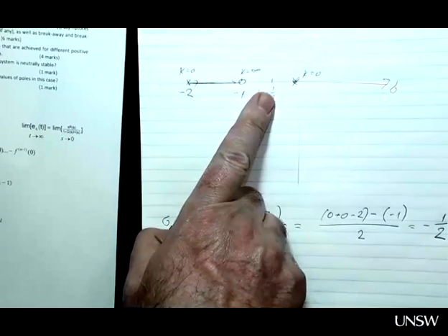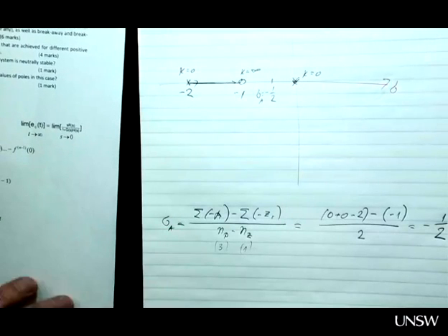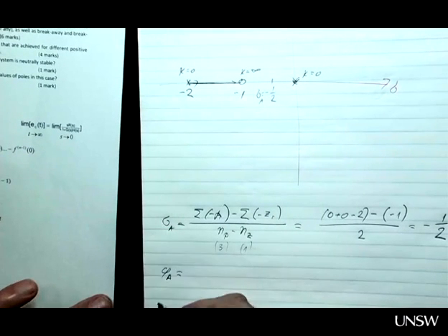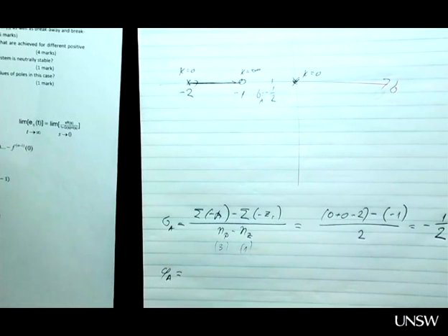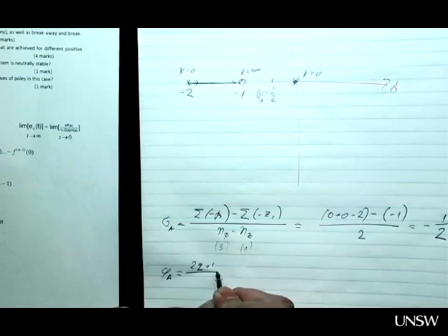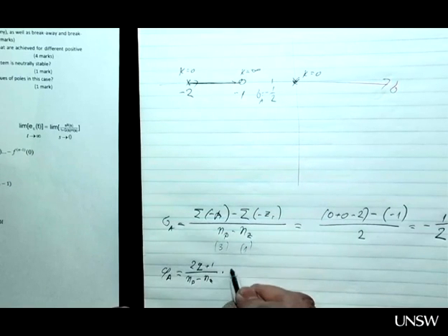Now let's see how many asymptotes. Phi A. By finding the angles, we also find how many asymptotes. Phi A is the angle between each asymptote and the positive direction of the real axis. That is equal to (2q plus 1) over (np minus nz) times 180. Yes?